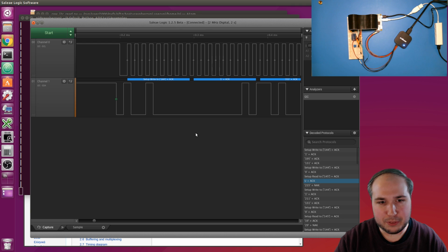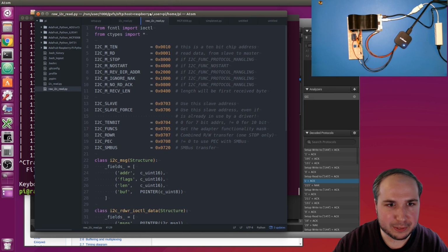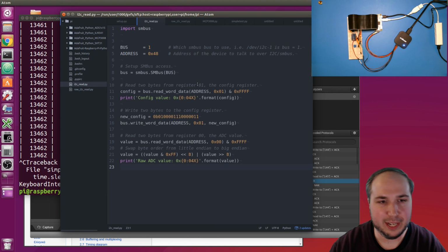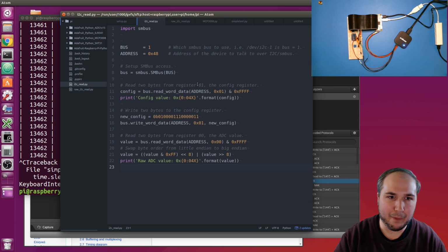I think what I'll do now is we'll jump in and look at the actual code that's making this work on the Raspberry Pi. So let's jump back to the Pi, and I have over here some code that I wrote earlier. Maybe we'll dive into this. There are 2 things I'll show as far as how to talk the I2C protocol from Python with the Raspberry Pi. I'll show a high-level way that uses a library called the smbus library, and then I'll show a lower-level thing, something I'm working on now, that's actually just using the raw Linux device that's exposed for the I2C communication bus.